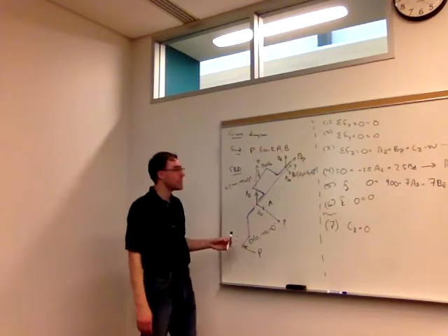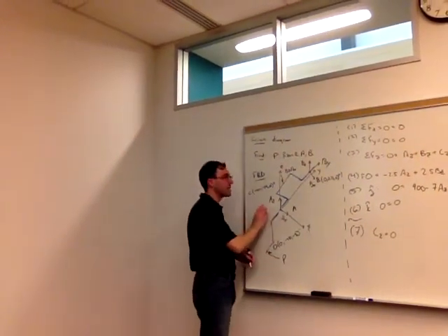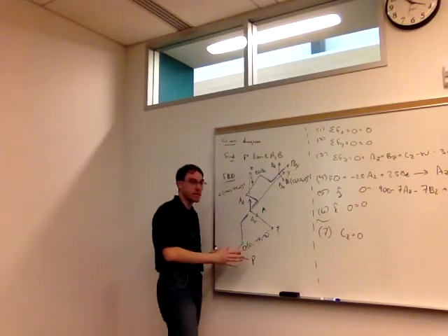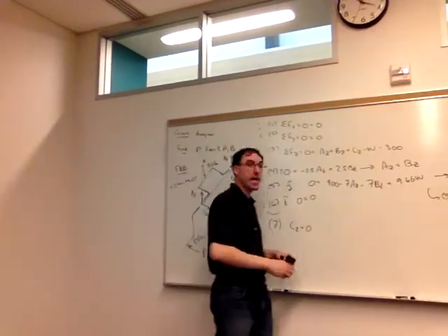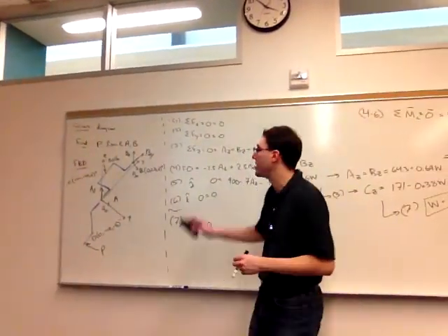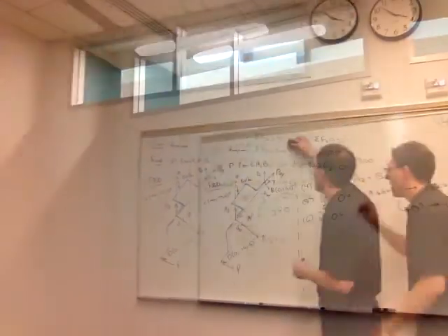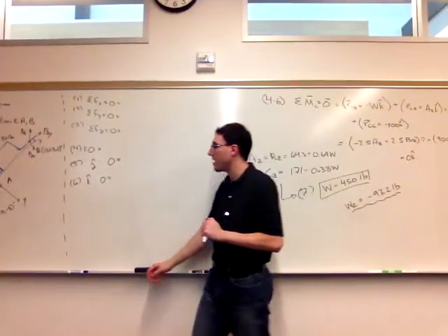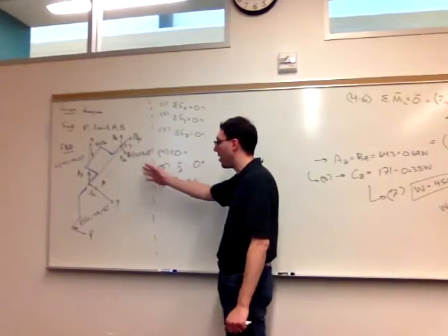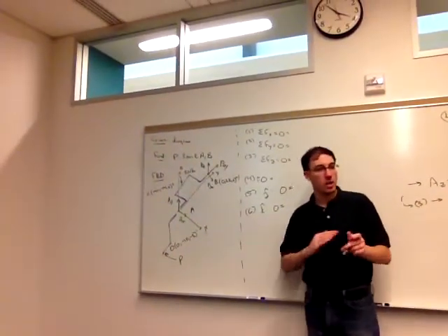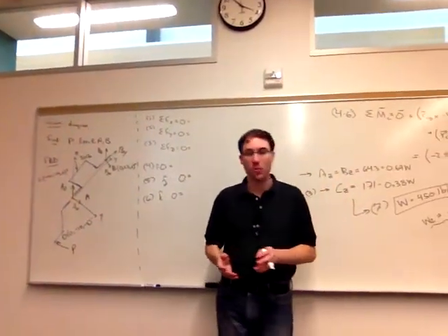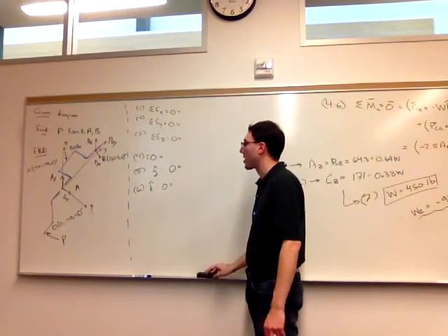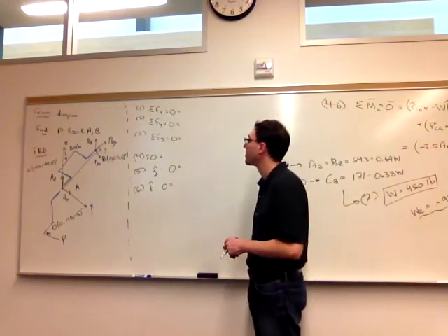So if we look at our free body diagram here, we have AX, AZ, BX, BY, BZ, and P as our unknowns. So 6 unknowns, and we can get up to 6 linearly independent equilibrium equations out of it. In this case, we don't need any of our unit vectors because all forces act along a coordinate direction, so x, y, or z. So we can jump right into making our equilibrium equations.